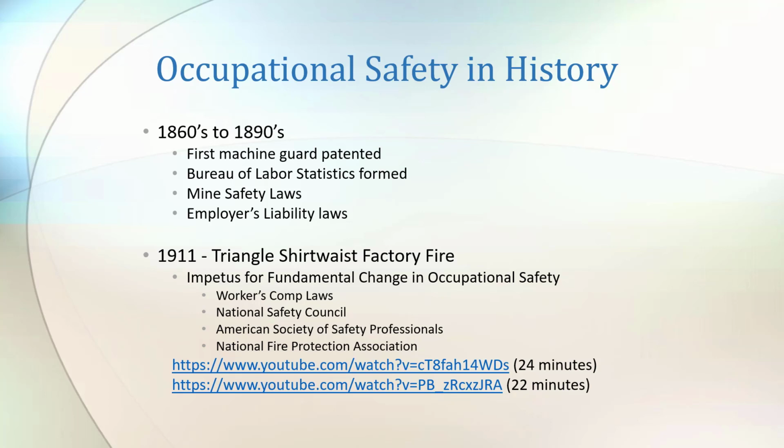That hazard could be a cutting blade, a nip point, rollers, any type of moving part, so a piston or any type of rotating part. That's what a guard is put into place for, to cover that up and reduce the hazard or eliminate the exposure, which we'll talk about a little bit later.